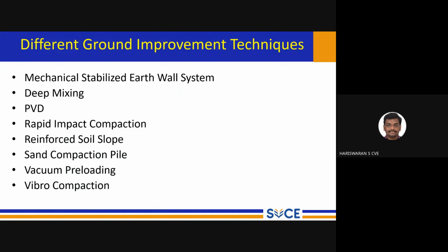This also plays a major role in geotechnical ground improvement. It is nothing but removal of water from the soil. That, for clay soil, is very challenging. Clay has the capability to retain water inside the pores, but it doesn't have the property to transfer the water or allow the water to seep.